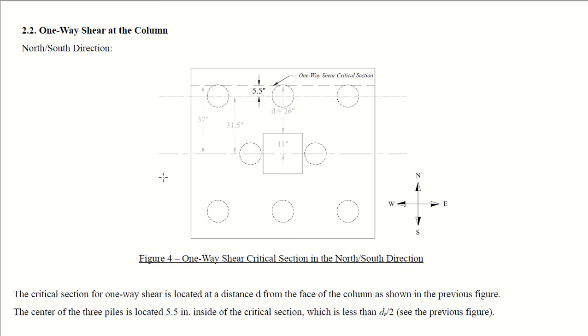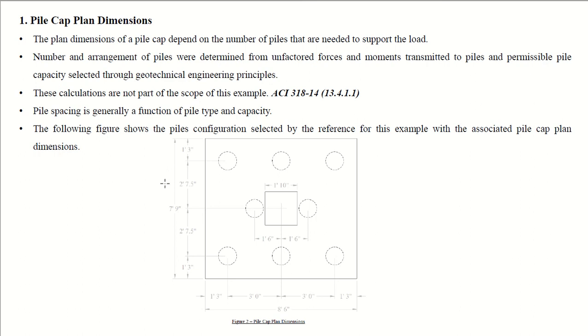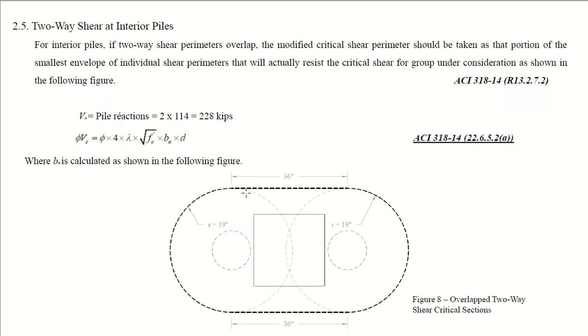Okay, let me take you to this figure again. For example here, okay, this is 7.75 feet total. When you divided by 2, you came to half, okay, the center line. You deducted this length and you deducted this 1.25. See, so this is the distance between here, the center line of these piles, to the face of the column. You are getting me?